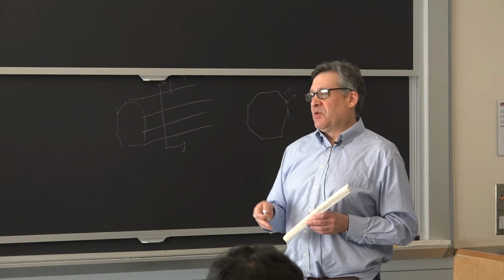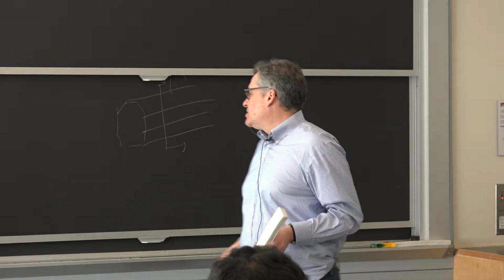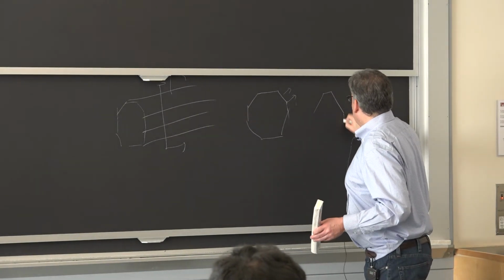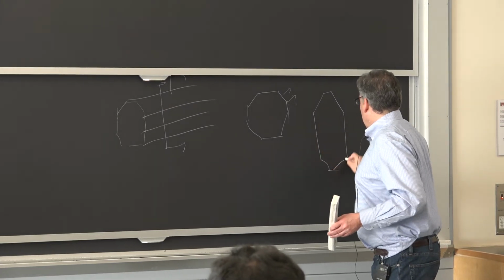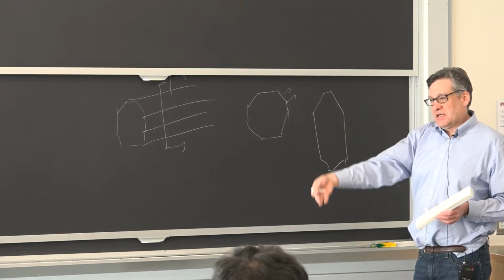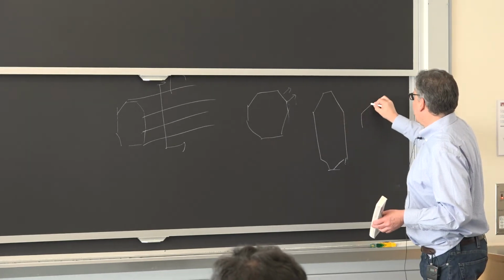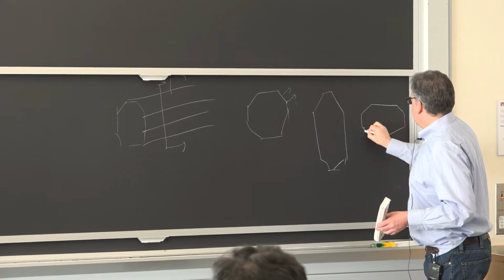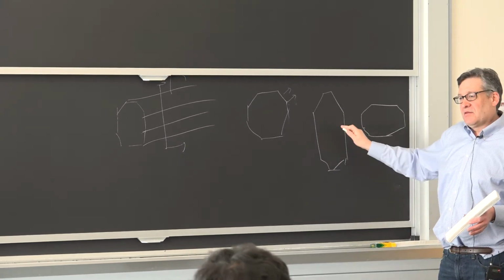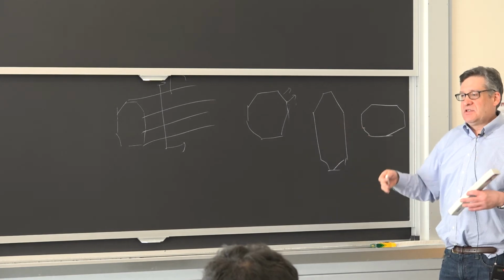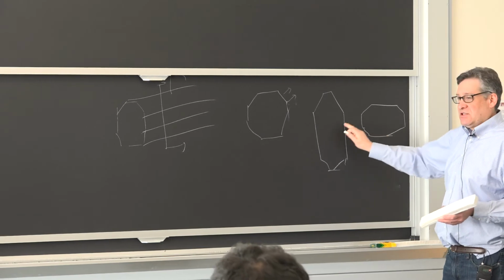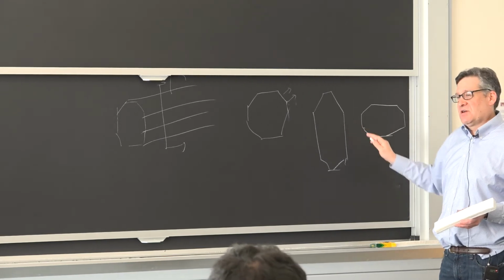Okay. So the perturbation vectors move around the cross-section. So, one time it might draw it like this. And it'll go through and calculate how much strain energy there is in that section given the boundary conditions. Another time it might draw it like that. The perturbations change the dimensions of the part, the cross section. Different angles, different displacements in or out. Make sense? Yeah. So the perturbation vectors are changing this cross section and determining what's the most efficient cross section.